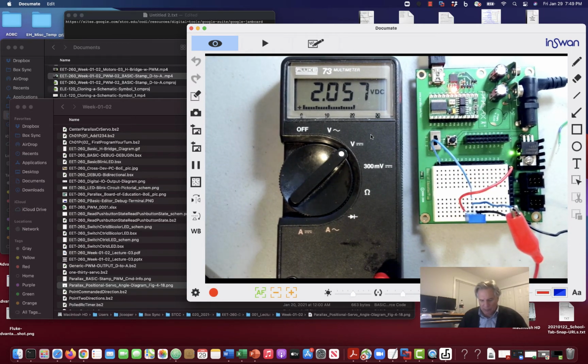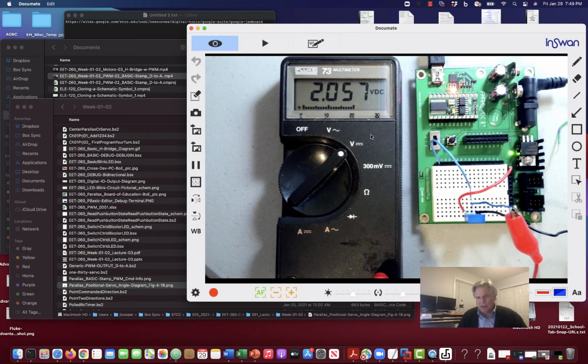When we drive a motor or an LED or something which either operates slowly, like that capacitor in the low pass filter, or a motor, or our eyes looking at the LED, we perceive to be able to control something at a level, even though it's really being controlled by a series of pulses.